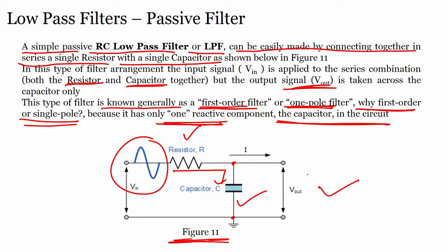This kind of circuit also gives you a phase shift. If you really want to understand the phase shift, which we have studied in oscillators, 1 RC will give you a phase shift of 90 degrees. If you adjust the values of R and C, you can change it to 60 degrees. In RC oscillators, we had 3R and 3C, and each one gave us 60 degrees of phase shift.